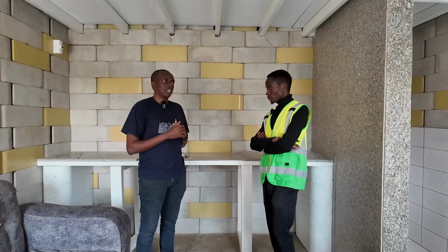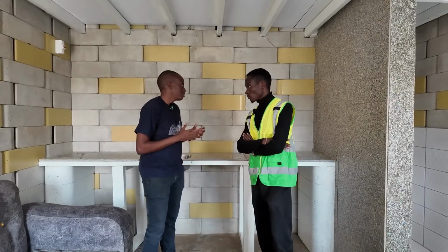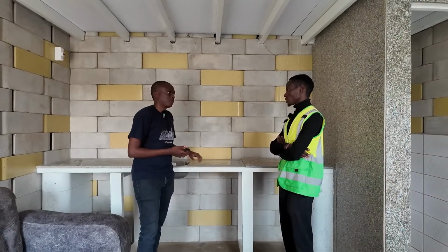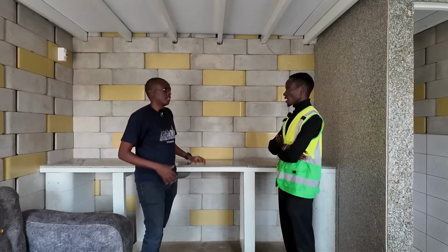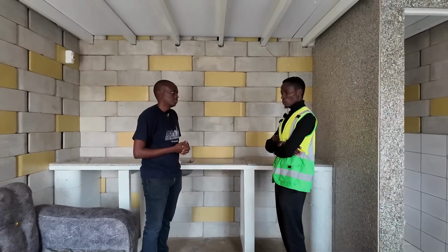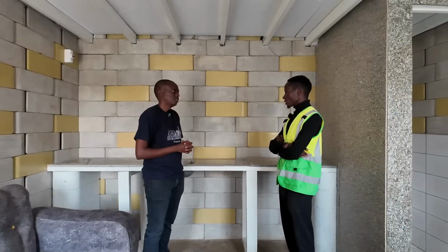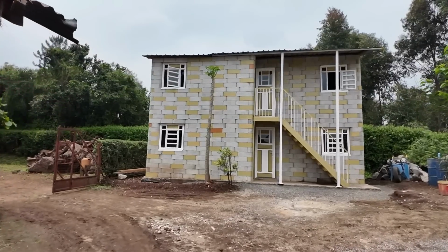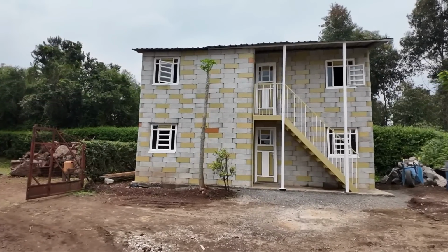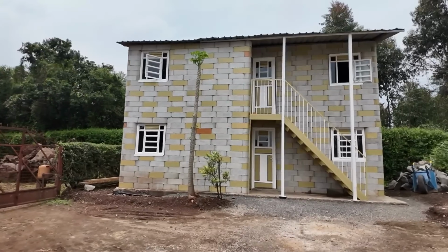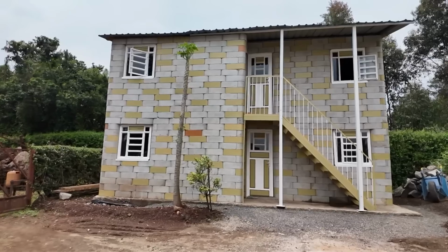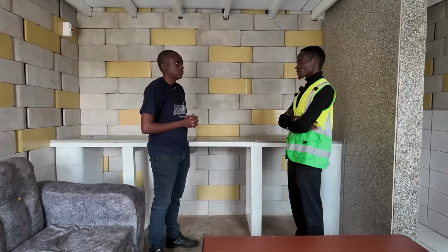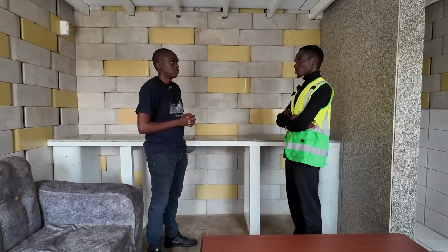Because I also have international clients, there are some clients who are watching who would like to know the earthquake performance of twist blocks. How do they perform in areas where they are earthquake prone? In areas where it's earthquake prone, the twist blocks are tried and tested. Recently, we've had earthquakes within Kenya, you can remember, and we've had buildings standing from 2018 till date. So it was tried and tested, and it works very well with earthquakes. Also, they are broader, at 250 mm in terms of broadness, so they are very stable compared to the other building blocks.